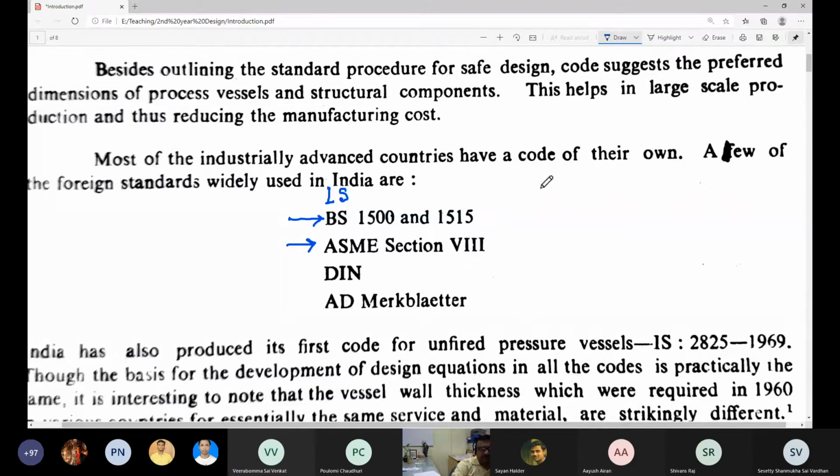So I was discussing the design of a pipe. Simply, it's the thickness of a pipe. I have already come up with a diameter of the pipe. How did I decide on the diameter? I have a flow rate. I know the velocity, what the frictional pressure drop would be, and if there are bends and other things, how that would work out, what kind of pressure drop I have. Based on that, I came up with some optimum diameter for that pipe.